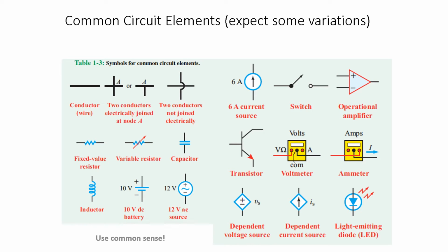Essentially, from a very basic perspective, an operational amplifier takes some kind of signal and amplifies it, makes it louder. But we can do a lot of different things with that. So there's differential operational amplifiers, which can take two signals and amplify the difference between them, which is used a lot in biomedical applications. We have a whole bunch of different amplifiers and ways of using operational amplifiers. You could do some really complex math with operational amplifiers as well, which we're going to try to touch on later in the course. But they're pretty cool. They're a neat little IC.